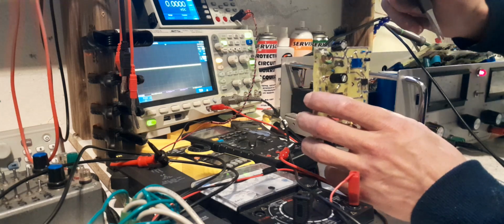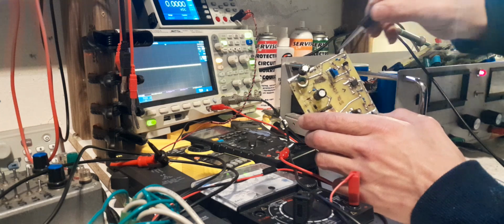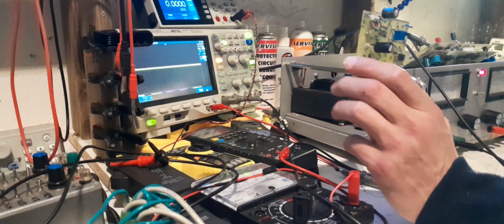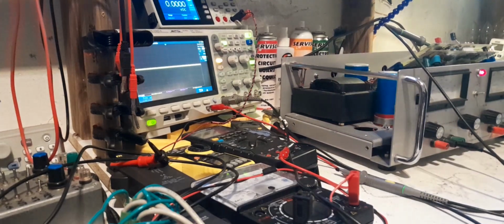Hold on, that's the cathode. In between the reference pin and the cathode, there's a snubber network there. So a lot of the times in certain applications, you need to do stuff with the reference pin. I tried pulling the reference pin via snubbers to both the anode and the cathode, and let's just say one made no difference and one just coupled more noise into it.